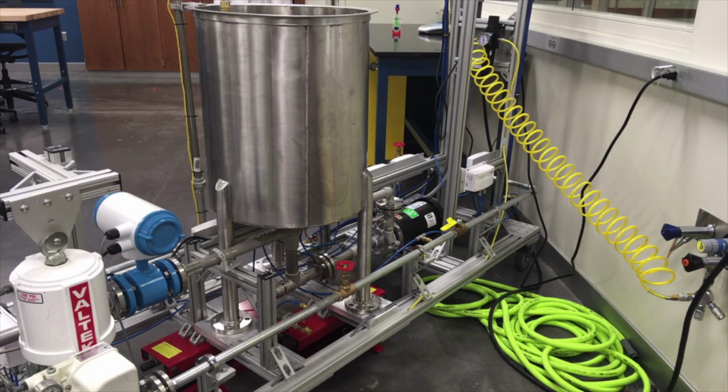So what I want you to do now is think about with your group what positions all these valves should be in when you begin the experiments, and which ones you are going to change. Also have a look at your previous schematics that had you examining the different pressure taps through the system. We did that in a previous lab experiment so that you can see where the pressure is being measured for this unit. Specifically, we're going to be looking at the pressure drop across the pump itself, so those taps are down here and then again at the top. For other aspects of this lab and settings you need to do, go ahead and pause the video here and talk it over with your group.